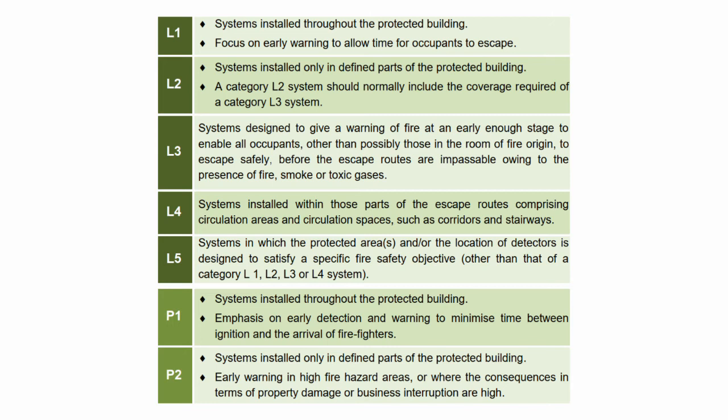If for any reason your system fails, you must still ensure that people in your premises can be warned and escape safely. Temporary arrangements such as gongs, whistles or air horns combined with suitable training may be acceptable for a short period, pending system repairs.